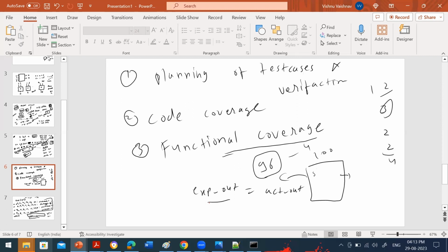You test some standard inputs which you think you should test. You test the chips under some temperature controls. You see whether your chip is working well under the conditions which you thought it should work. You even vary them. You try to inject some noise, and vary some voltage, and make sure it works well from all perspectives, which does not come in DV, like temperature and voltage variations. It does not come because it's all at the software level.